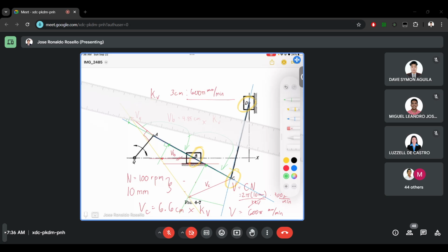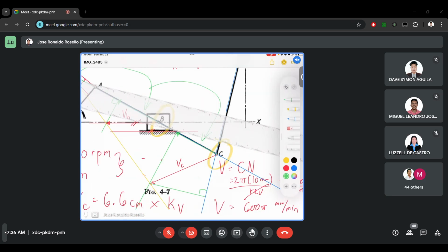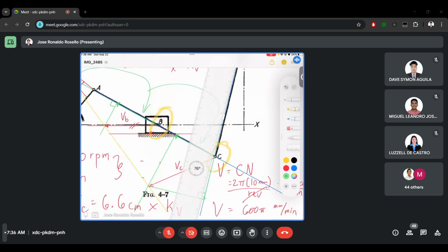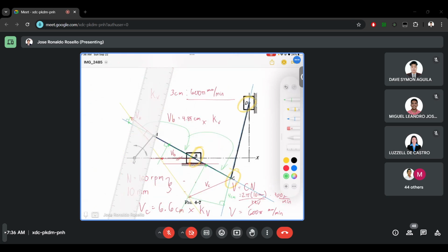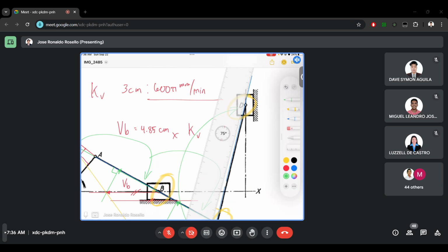This is the perpendicular component. Then we'll make the along the line component. Then we'll measure this along the line, which is around 1, 2, 3, 4 centimeters, and we will copy it to point D. So to copy it, let's make a 4 centimeters here.